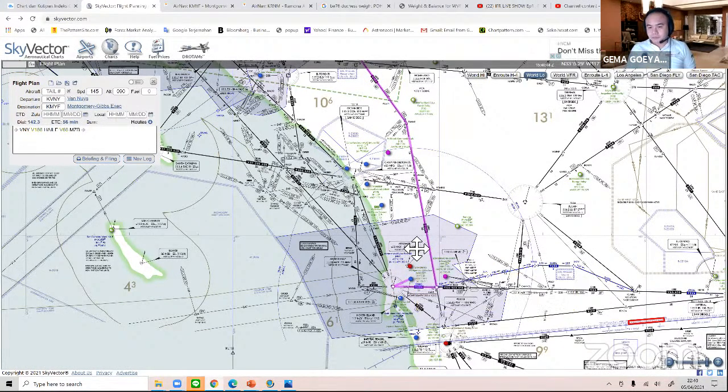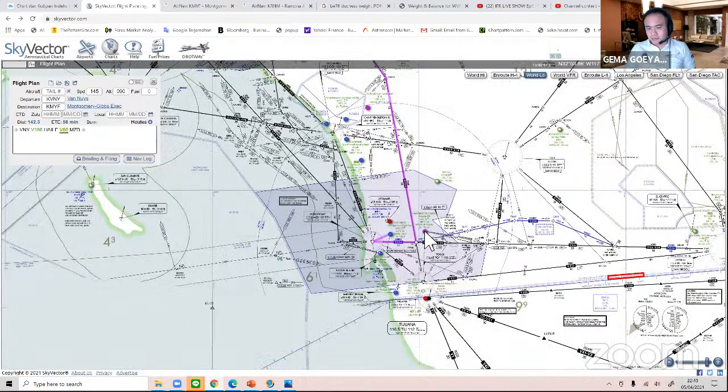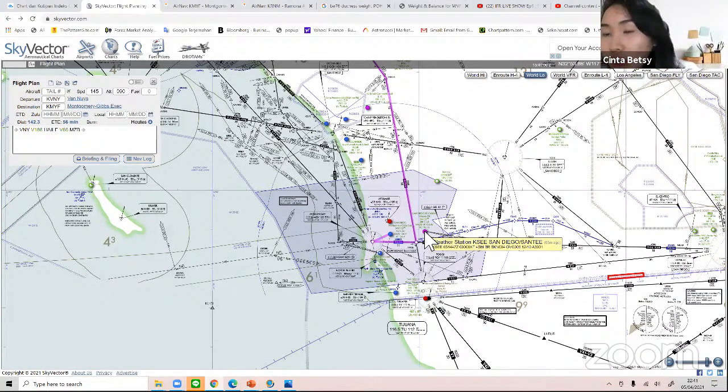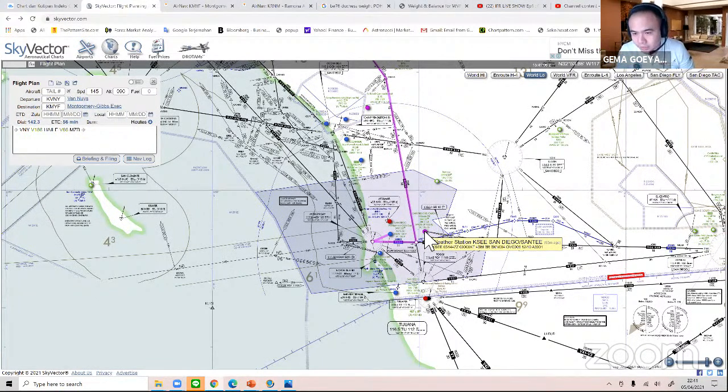Okay. Now, this is SEE. It's still magenta. It means this is a low IFR. So what's the ceiling now, Chinta? The ceiling now is broken 400. The wind is no wind at all. Visibility is 4 statute miles. Basically, the visibility is clear. I mean, it's on the marginal. Okay, it's not really bad. It's above 3 statute miles, but it's missed. BR, it means mist.